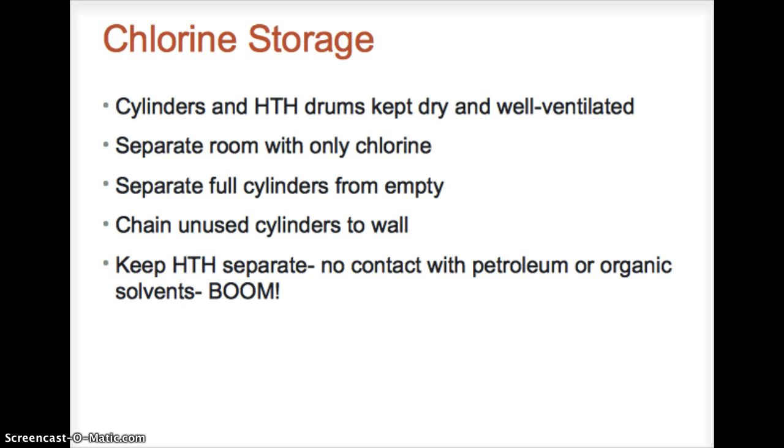And this is a little bit of a repeat. Cylinders and drums of dry chlorine should be kept dry and well ventilated. A separate room with only chlorine. Separate your full cylinders from your empty ones. Chain your unused cylinders, gas cylinders I'm talking about, to the wall. Keep your HTH separate. No contact with petroleum or organic solvents. Otherwise, you could have an explosion. Boom.